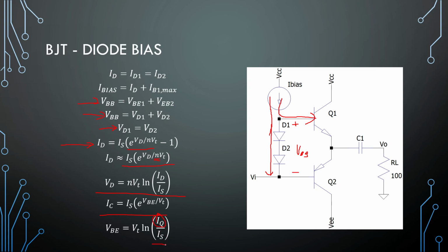So the saturation current right here you will find in the SPICE model. And you need to calculate that independently for each transistor, unless it is matched transistors, then this IS will be the same. So typically you try and match your components in any case.